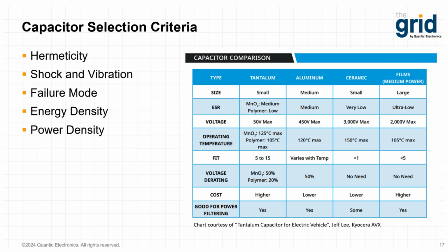All these factors should be discussed with the capacitor supplier to make sure that the capacitor chosen for the unique application meets the design criteria for derating and performance and everything in between. Moving along to energy density. So the energy density is the amount of energy stored in a capacitor per unit of volume. This is a key component. The higher the energy density, the more volumetrically efficient the capacitor is. The capacitor's energy density is calculated by dividing the energy stored in the capacitor by its volume.